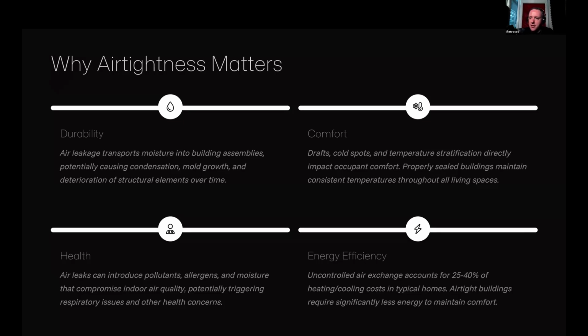And that really dials into health too. Indoor air quality really falls under that. So if we're growing mold, if we're bringing in particulates, if we're sharing a lot of air with dusty vented attics or moldy crawl spaces, if we're bringing in pollutants from the outside in urban areas, we're really just setting ourselves up to feel really terrible all the time. So we really want our buildings to isolate ourselves from those harmful areas. So we really want to keep them a healthy space, and to control that, step 1 is an airtight envelope.